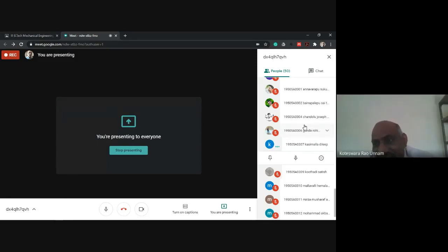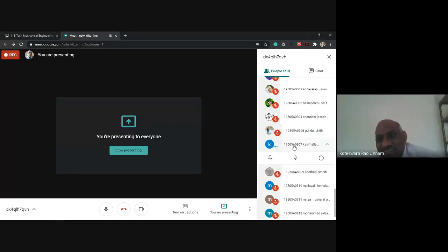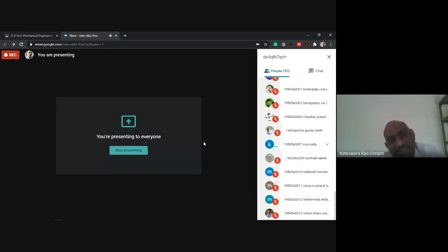That means what you want to say is, if the load is tensile load, you have to take tensile strength. If the load is compressive, you have to take compressive strength, right? Yes, sir. Okay, very good. So that is the answer. So don't say that only ultimate tensile strength you need to take. Suppose the component is subjected to a compressive load, then it is subjected to a compressive stress. In that case, you need to take ultimate compressive strength only. When the component is subjected to a tensile load, it will be subjected to a tensile stress, then the criterion should be tensile strength.